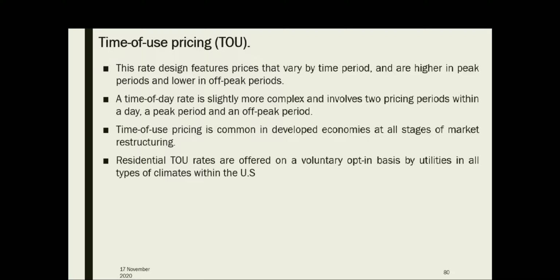But in a block rate tariff, the scheme differentiates between the customers based on the quantity of electricity consumption. So there will be different levels. The scheme consists of multiple tiers characterized by the amount of consumption. That is what is actually happening in our system. There are different blocks, and each block is priced at a different energy price. Then there is the seasonal tariff, which means that the energy prices will be different for different seasons.